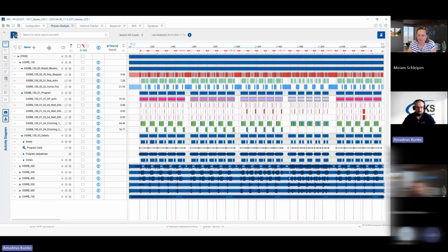The idea was that every line, at least these lines, where robots are working so tightly together, have some interlocks in between. One robot requests an interlock, and the other robots are waiting until they can go inside and do their thing. These interlocks we had a look at, and so we started out by doing some basic things.